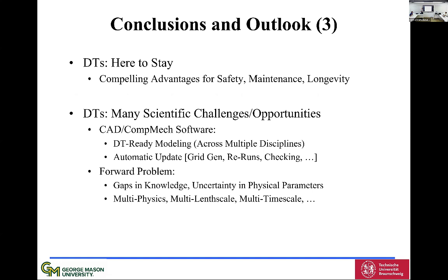Okay, so if you think about CAD or computational mechanics software, we've so far concentrated on CAD. But if you think about digital twins, you should have a digital twin ready modeling. Okay, so that if in the future you have to change something, it's not a pain. Because if this is going to be complicated, it's not going to happen. So think of the CAD digital twin ready model, not just the CAD model. Okay? Because we want to do automatic updates.